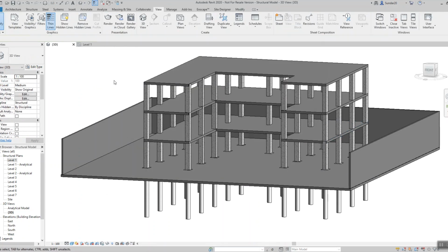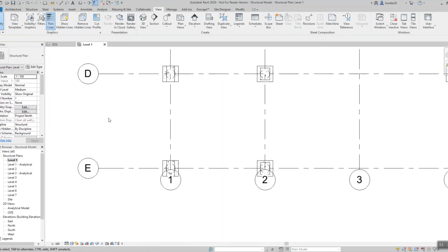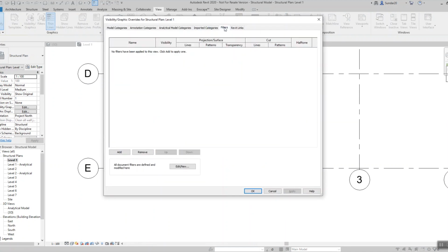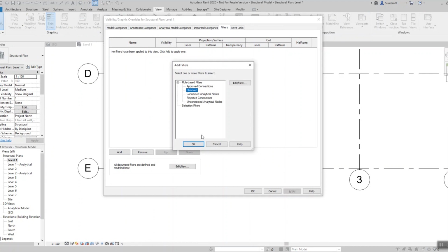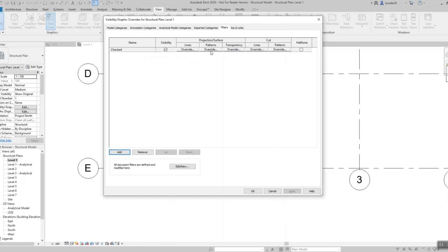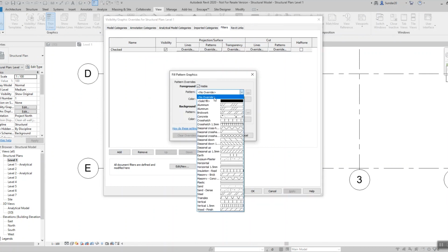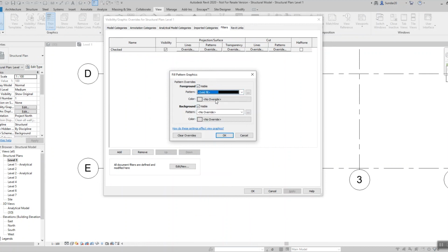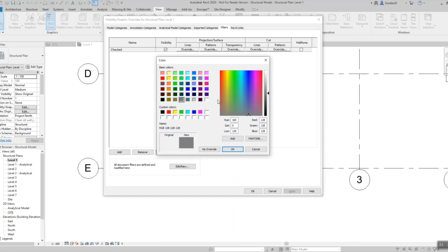And when you go to a plan view, there also you have to generate the parameter. So don't forget that. You have to add the parameter. The same thing you're supposed to do even with a view template; this has to be created separately for plan, elevation, and 3D.